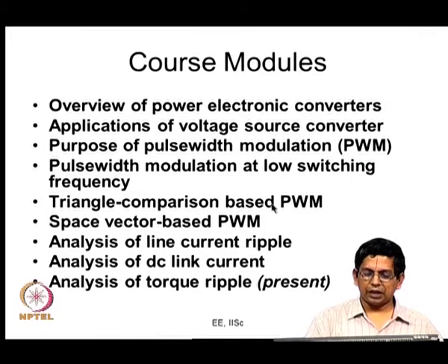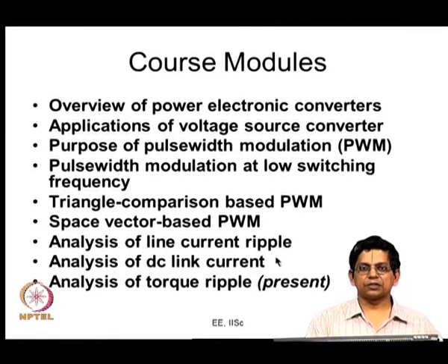After we did the high frequency PWM, we did the analysis of line current ripple. In some sense there is some similarity between the analysis of line current ripple and the torque ripple, like we would see today. Alright.